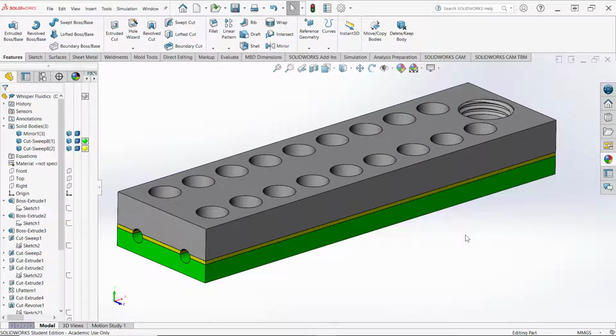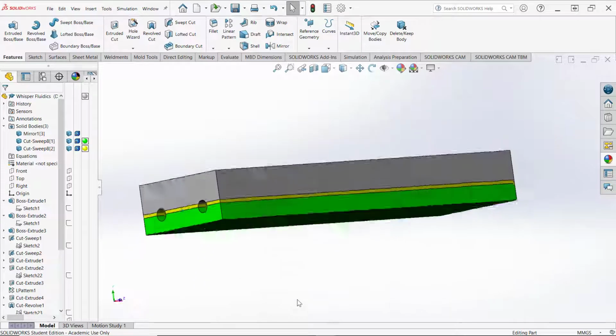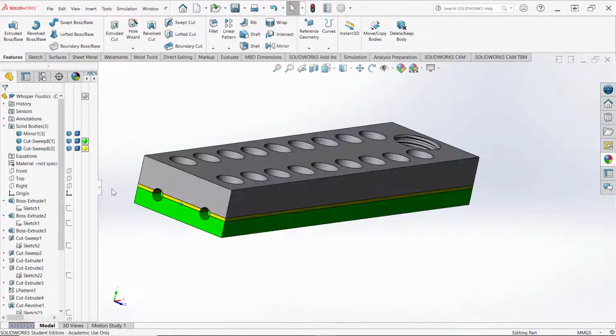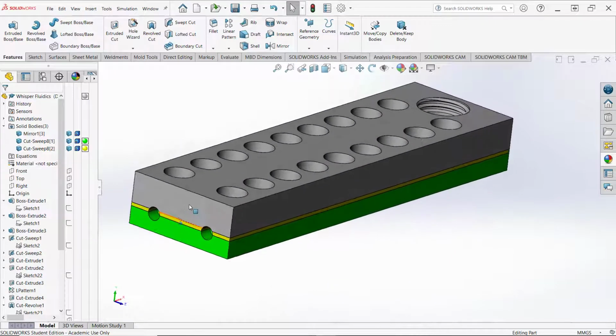And then you can also put those into the assembly. Because everything was match machined together, the easiest way to make that is, well, it's going to come into the origin anyway. You could just ground it at the origin, or if you have some moving components, mate it to the origin planes. In any case, we know everything is going to match up perfectly.